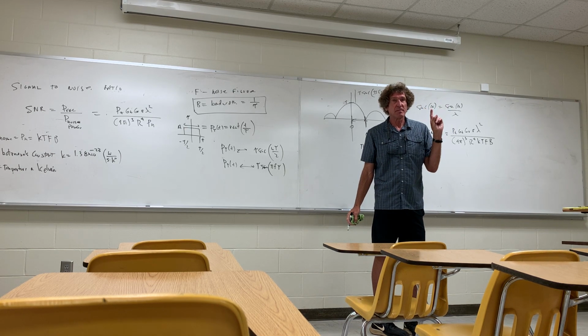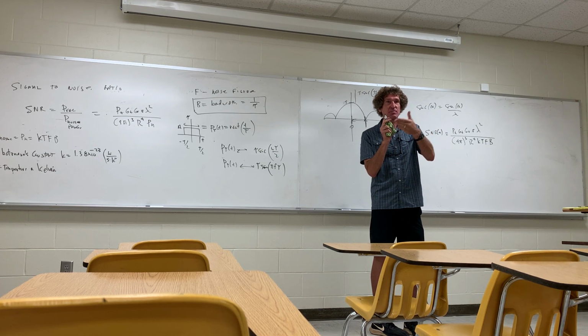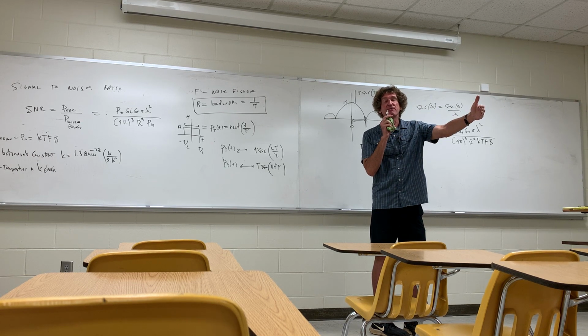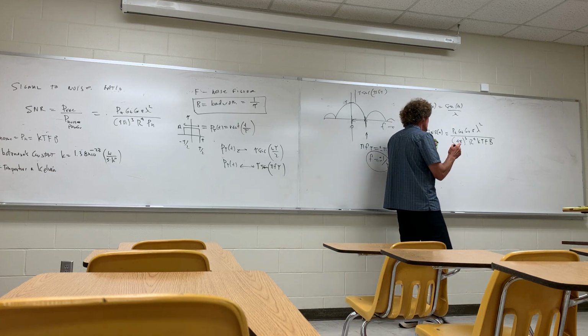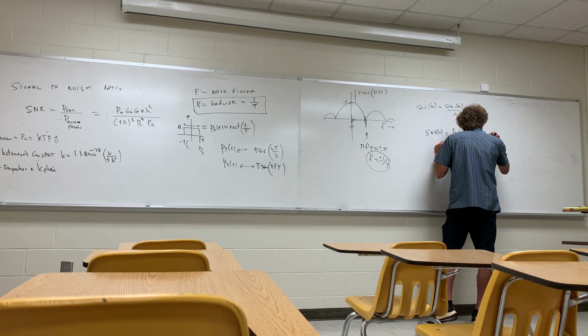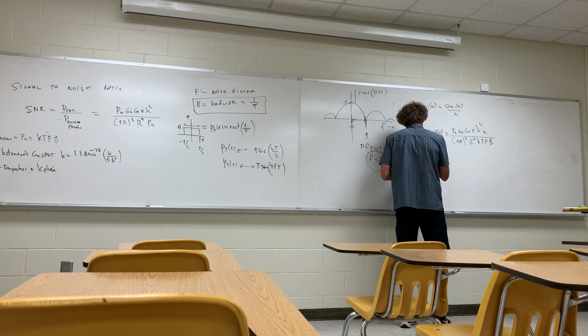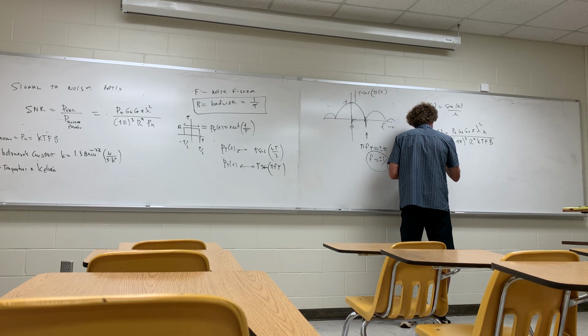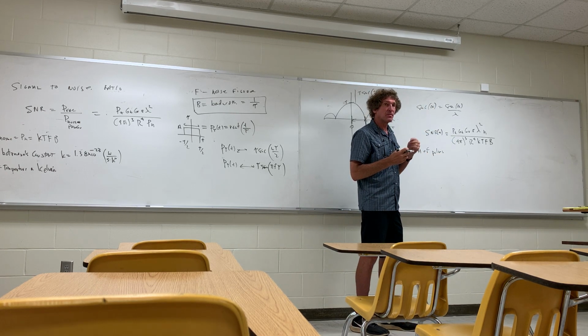Now, without getting into the mathematics, we do something where we really have coherency, and I'll explain this in a second, but when we add the effect of multiple pulses, the noise power is not additive, but the actual receive power is. So then if you multiply this by the number of pulses, n being the number of pulses sent, then you get the signal to noise ratio for the number of pulses.